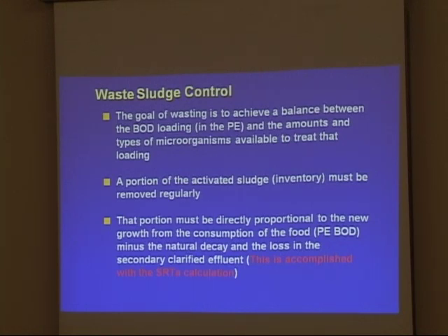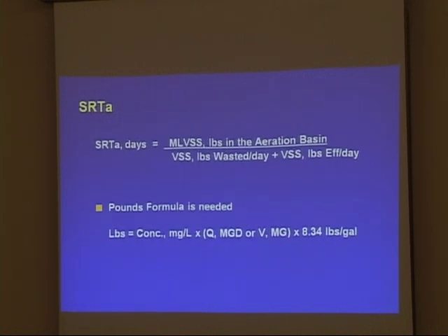That's the SRT aerobic calculation. So in this, you're going to use the aerobic volume that's out there. So if you're running the A2O mode, you would not use the anoxic selector or the anaerobic selector's volumes in the calculation. You'd use only just what's aerobic. And so if you're consistent with that, that's how you can calculate your efficiency.